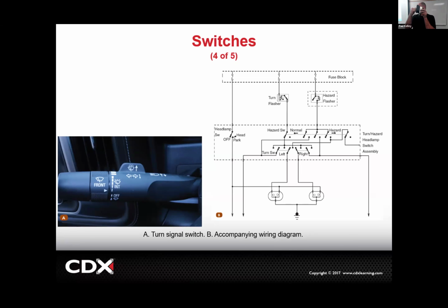But these are generally not made to be taken apart. We can go right to it where we can disconnect and reconnect it, and there's a connector there, and we can do some back probing and stuff. But when you learn on the board, you're going to start with stuff like this to get the concept, and we're going to work our way toward the car, where you're looking at something more like this, with 40 wires going in, and you have to make sure you're on the right terminal when you do the test. So there's a building up to that point. It takes a little time.